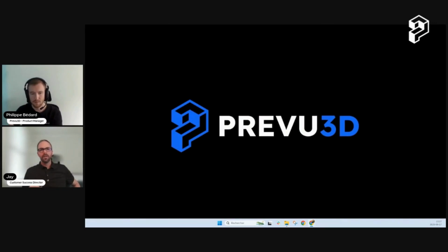I think the bigger issue a lot of times with piping is it's close to the ceiling or close to the wall, and the negative space, the space in between you and your LiDAR sensor and that wall, you're not going to capture. So with the bounding box, you can do that, and sometimes, depending on your line of sight from that LiDAR sensor, you'll actually get as complete as possible that piping aspect just by moving that box out a little bit more.